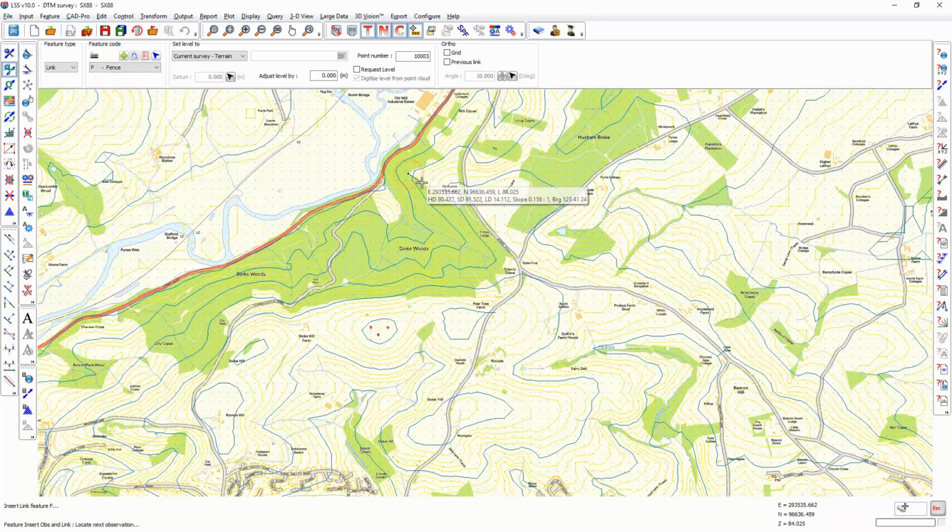So I won't do the whole lot, I'm just going to do a small area. Let's follow along, roughly along that road. Clearly you would do this much more accurately than I'm doing. If you've purchased the vector data, such as the master map data, then this woodland will already be defined by a line. It may well be 2D, and you could drape that onto the LiDAR DTM, and then you would simply just have to define this area with a specific height, because it would already be coloured in. Let's just finish this off. Again, forgive me for being so rough with all of this.